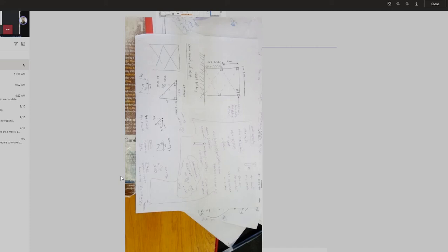The critical one is to show that we should have a member over here, because this member will work in compression. So if you put a small member over here, say for example, if your rafters are 190, the other critical thing which needs to be checked is that that particular member should be checked for compression too. Does that make sense?